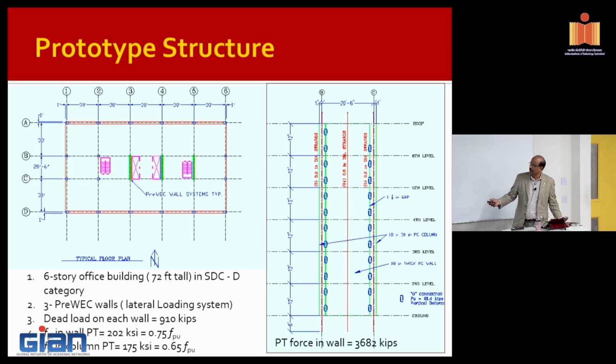These are all what they call a gravity load resisting frame. So the goal is to take the load and transfer it to the seismic frame. But if this frame is moving, say it's designed to move by say 150 millimeter, these columns have to go through the same movement as well so that they don't collapse or they don't unseat beams.